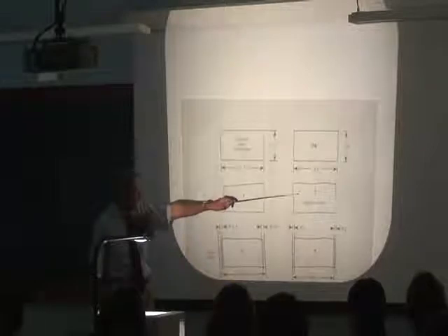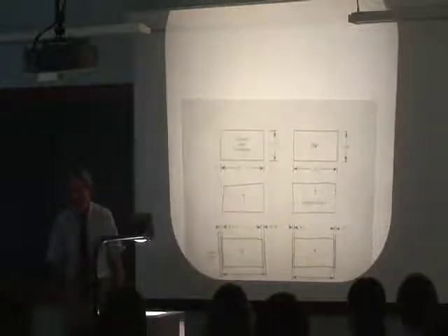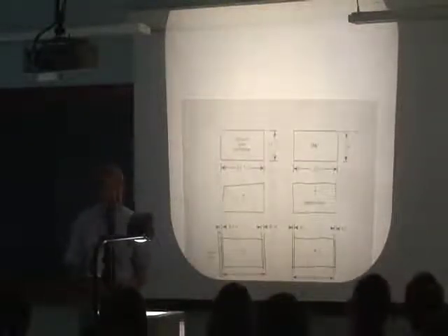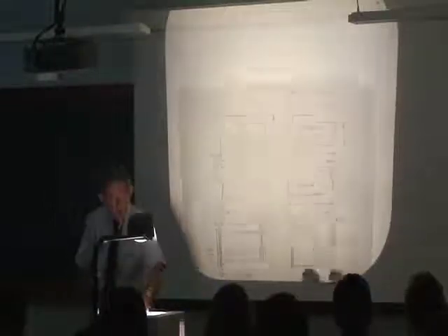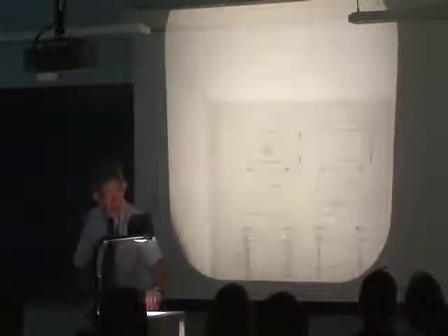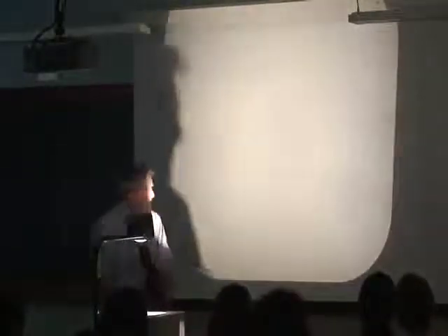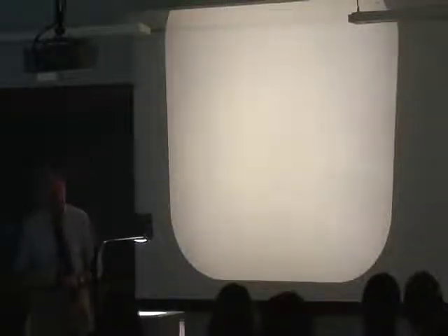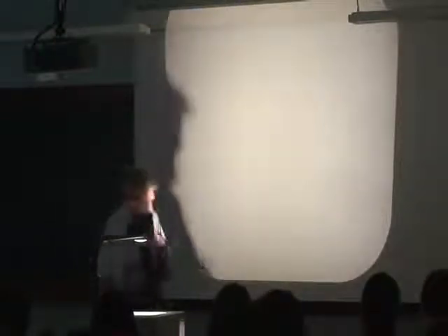If you produce a part of imperfect form, what do you do with that? And everything you make has imperfect form. There's no such thing as a perfect plane or a perfect hole. You have to deal with form. And, well, the kinds of ambiguities you have and the attempts to deal with them are shown there, but suffice it to say there is no way to fix that limit tolerancing drawing you just saw without changing basically the way you approach variation control. What's happened since then is that we've gone to geometric tolerancing, which is a different sort of a system. I'll show you an example of it.